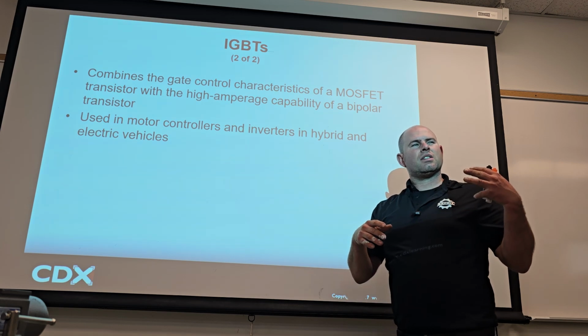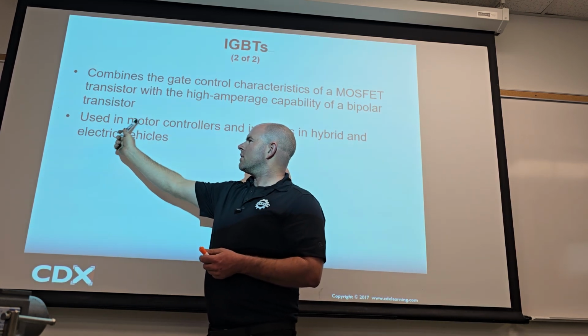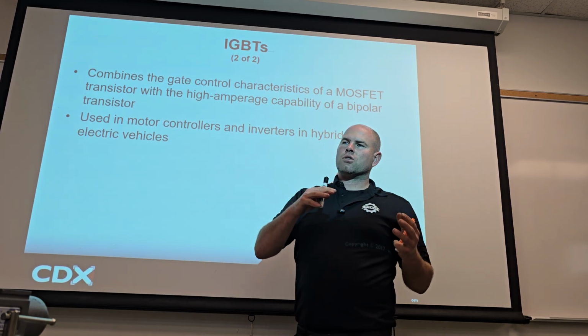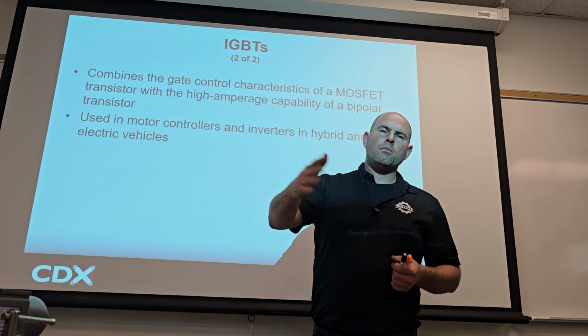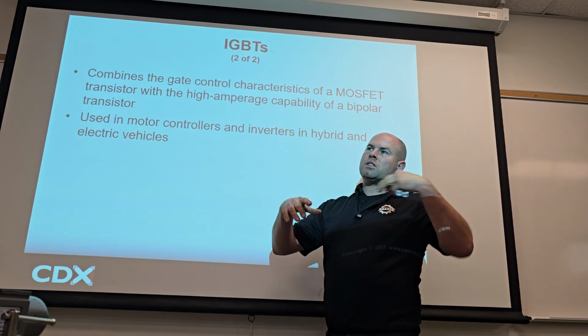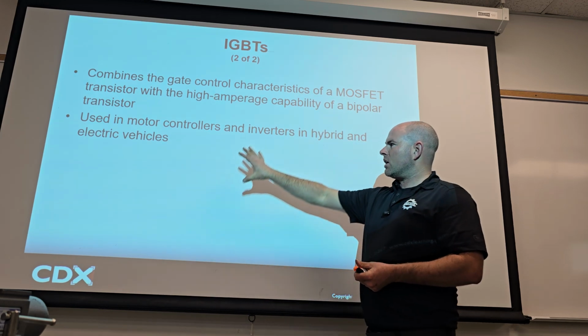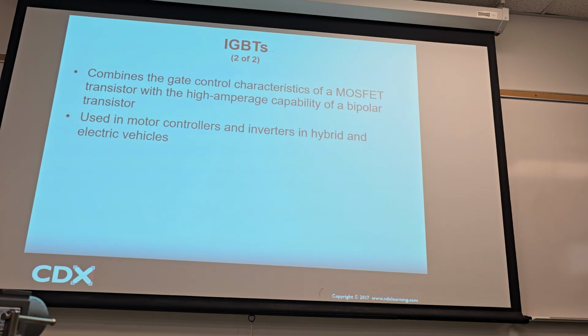That's not just inverting, that's motor controller. Make sense? So the inverter does invert, but it also controls the speed of the motor, speeds it up, slows it down. Speeds it up under load, meaning it's a motor, slows down the frequency enough to become a generator, and that's our regenerative braking, right? All that electronics we commonly call the inverter, but that's a little misleading.